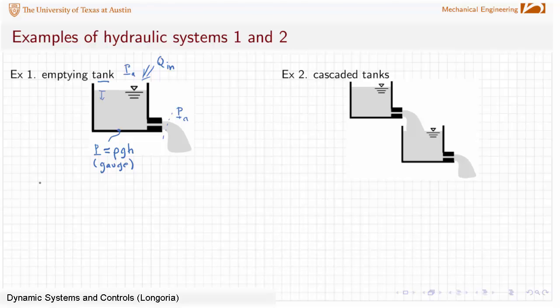Okay, so this allows us to say that if I look at my control volume, I can then just write an equation directly, right from continuity. I can say that the rate of change of the volume in this tank, right, is just the flow coming in less the flow that's coming out. And let's say that that's Q0 here coming out. That's one equation. And remember, it's not a state equation yet because it's not in complete form. Now, this is an input, so we're done with that.